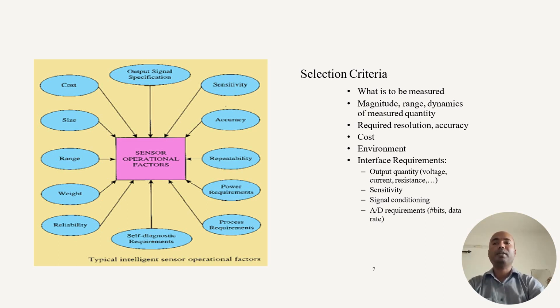The very good example is knock sensors. While the engine is vibrating, from that vibration it produces the power volt. That power is developed into a signal, processed, signal conditioned, and then given to the ECU. So those kinds of sensors don't require any power supply for their working.